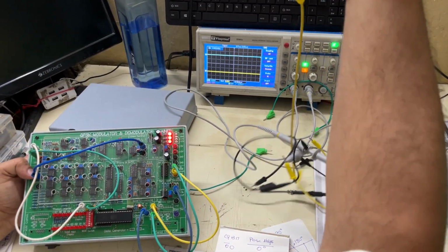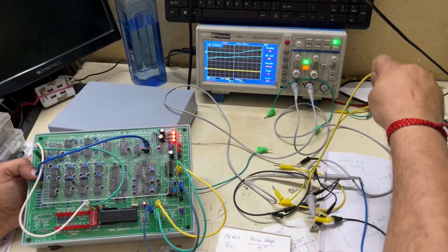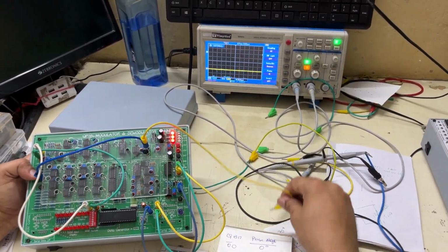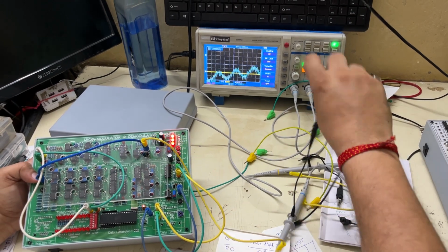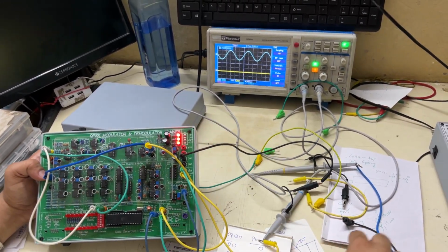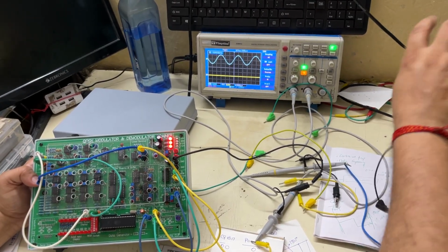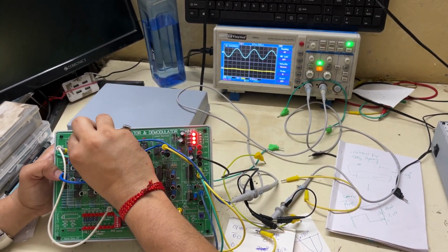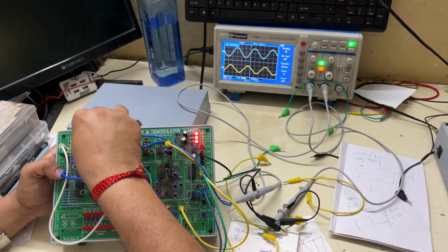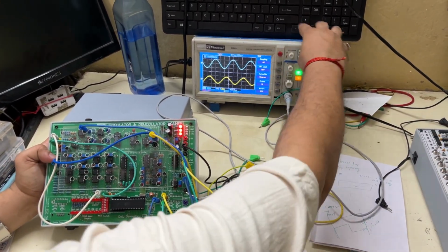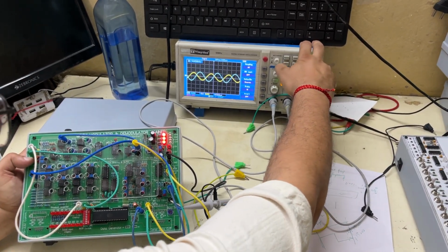Now comes the connection for our DSO. This is my QPSK output DSO connection, this is my ground. Then comes the second probe which goes to the reference. Now what I have done is, on yellow we have the reference input and the blue will be our output. We'll set them both to 0.